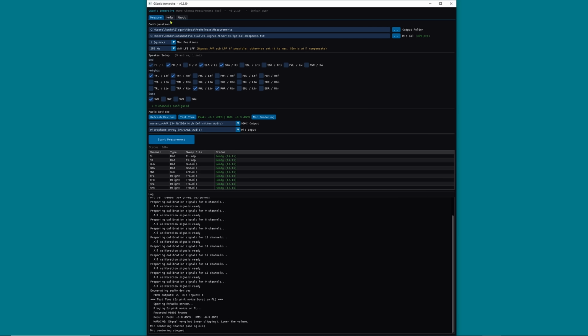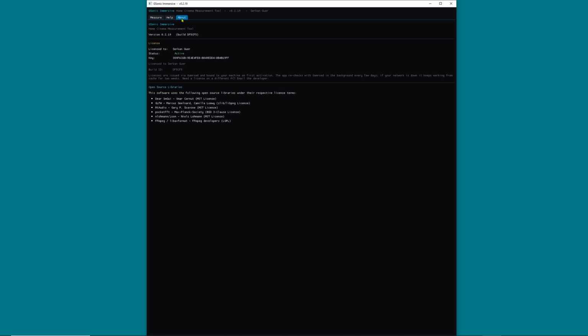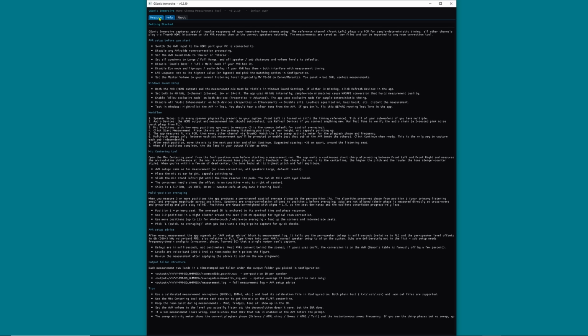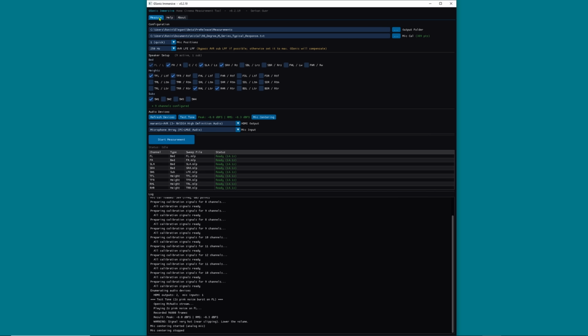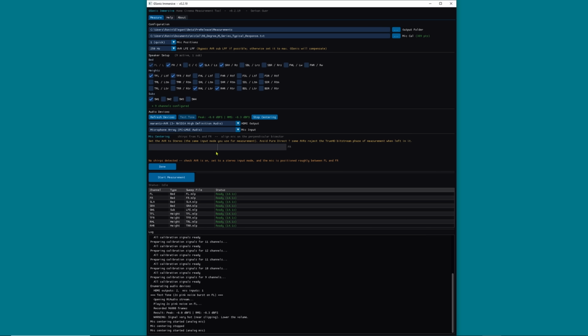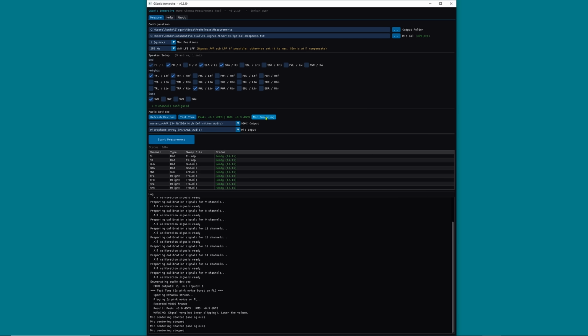If you have a Denon or Marantz receiver, GSonic will detect it automatically. It will not generate an ADY file for other brands to avoid confusion. Regarding mic centering, if you are using an analog microphone, including Odyssey mics, you can adjust the placement in real time very precisely without needing to look at your monitor. Since it's difficult to see your computer screen from the MLP, the app uses audible pitch cues to help you easily center the microphone blind.